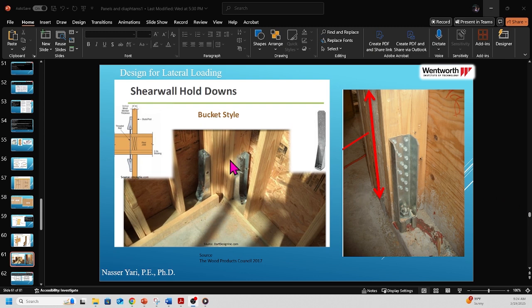So when you look at the corner of the shear wall, it's all doubled like this one here, because a single 2x stud will not provide enough adequate thickness for the fastening to the anchor bracket. So you need it thicker than one single 2x. You need probably 2 of them, or a 4x member. That way you have a good connection for the tie down. And a lot of time in construction anyway, they double these corners. So that's what I mean. This chord, we're going to double it too. So let's go back to the writing again.